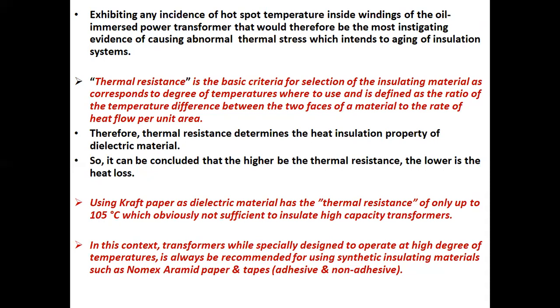Thermal resistance is the basic criterion for selection of the insulating material according to the degree of temperature to be used, and is defined as the ratio of the temperature difference between the two phases of a material to the rate of heat flow per unit area.